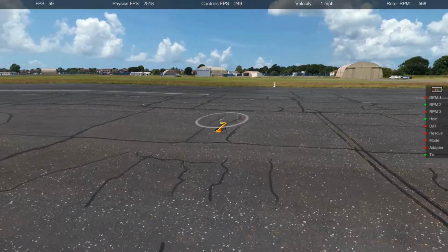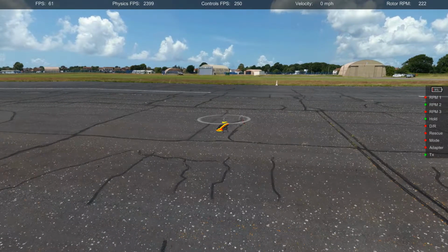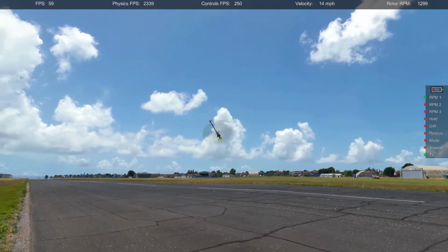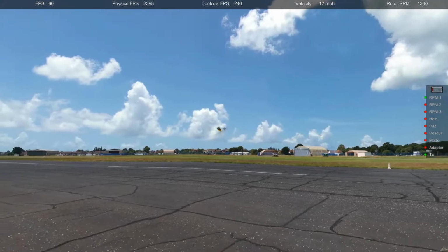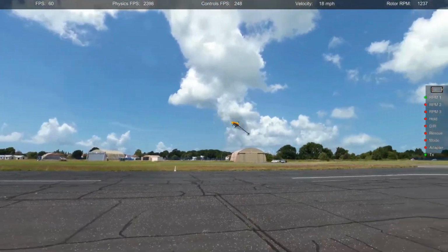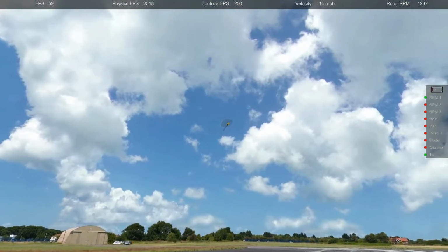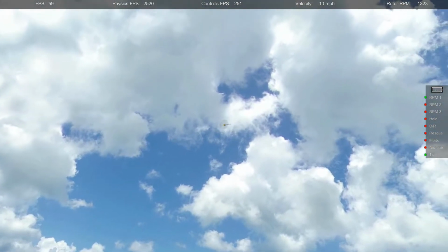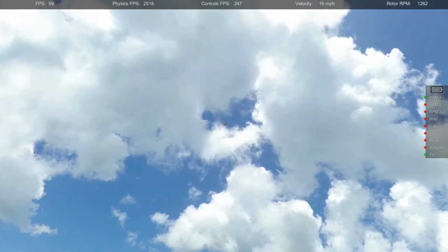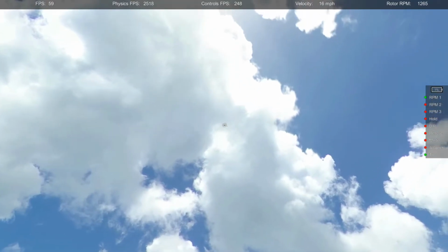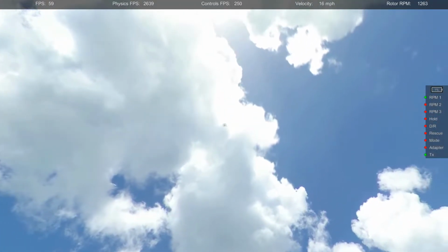Prandtl said, instead of thinking about a 38-foot span wing, now I want to carry the same load, I want to carry the same G limits. I have 450 pounds of aluminum. What's the minimum drag I can get out of 450 pounds of aluminum? That's this new curve C. If you want to find the minimum drag for a given amount of material, this is the paper you should use. And in fact, it's 12.5% higher in L over D than the elliptical solution.